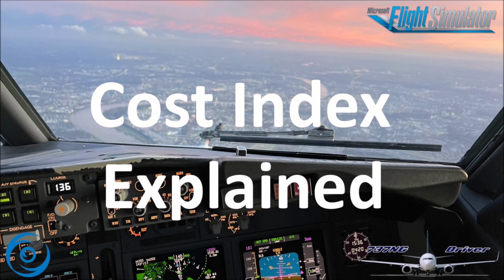If the said airline would adjust its cost index on the 737-400 from 30 to 12, the average 1,000 mile flight would just take a single minute longer, and the annual cost saving would be in the region of approximately $771,000 US for a single more minute flight time. Now let's have a look at the 737-700, where the current cost index of that operator was 45, and the optimum cost index would have been 12.